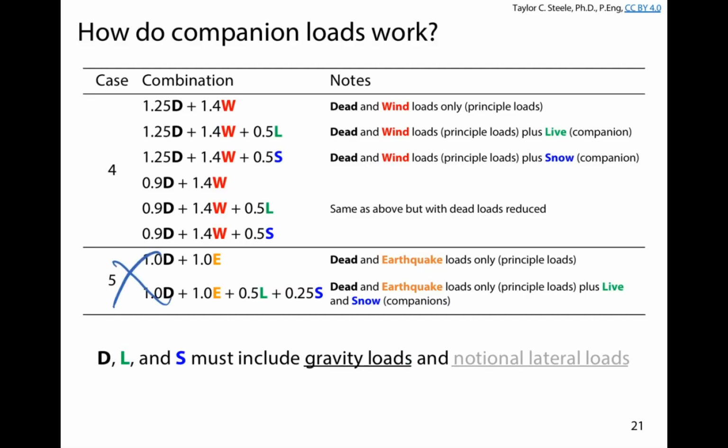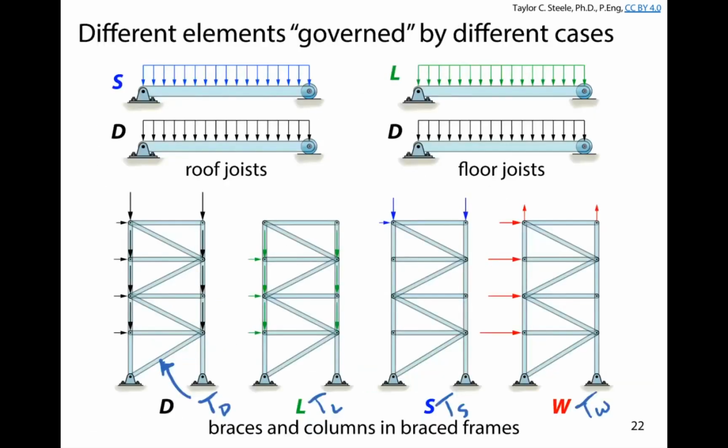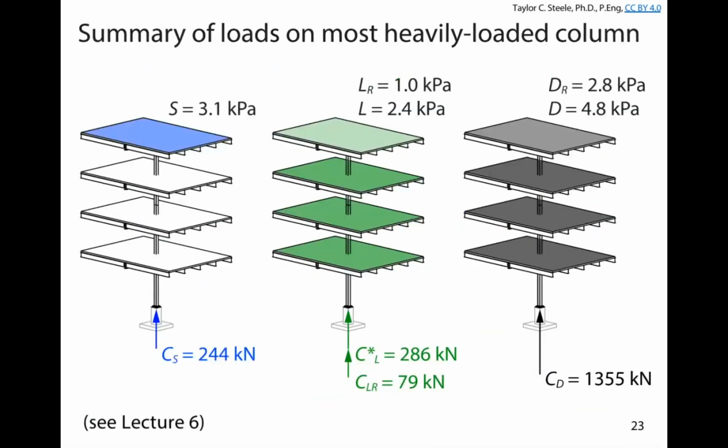We've got wind load. Why are we not considering wind load in our load combination perhaps? No, that wouldn't be why. If you looked at the example lecture notes, we do have the potential for an uplifting wind suction on the roof, right? And so it is possible that the wind is going to be at the roof level pulling up on that column, okay? So go look at the example lecture notes from lecture 7. We have a suction on the roof that might pull that column up.